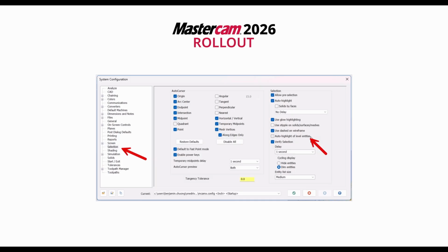Mastercam 2026 also adds a new config option for levels in the selection topic of the config. You can now auto highlight entities on a level just by clicking on that level. It does display the same as selection, but the entities are not selected, so this may be an option you want to turn on as needed if you're trying to find a component of a large assembly.